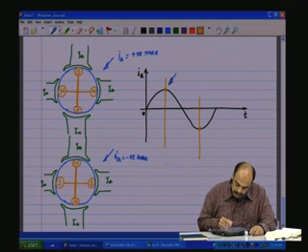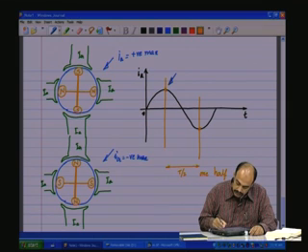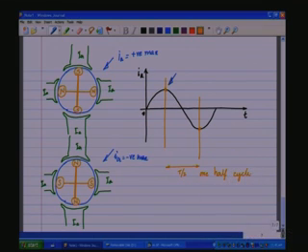But however, here you have one complete half cycle, T by 2. That is one half cycle. So one half cycle makes the MMF rotate by 90 degrees, and to get 360 degrees you need 4 half cycles, or 2 cycles, to complete one complete revolution of this one.